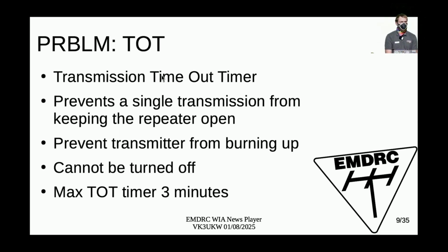So the transmission timeout timer, pretty much every radio has that. It means you key up, and after a minute or two or three, the transmitter just turns off until you release the PTT and let the transmitter cool down. It prevents a single transmission from keeping the repeater open, even though it blocks the repeater completely, which in a single frequency system you can't avoid anyway.